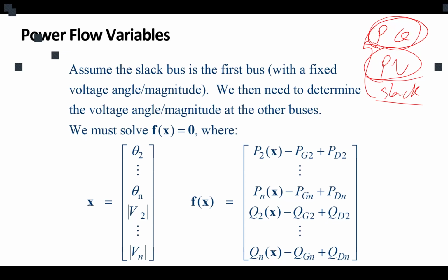I have my reference bus, one for my per unit. Do I put that, or do I put the deviation that I want? No, a slack bus is always 1. In the load, say I'm using bus 1 as my reference, so I want that per unit as 1.